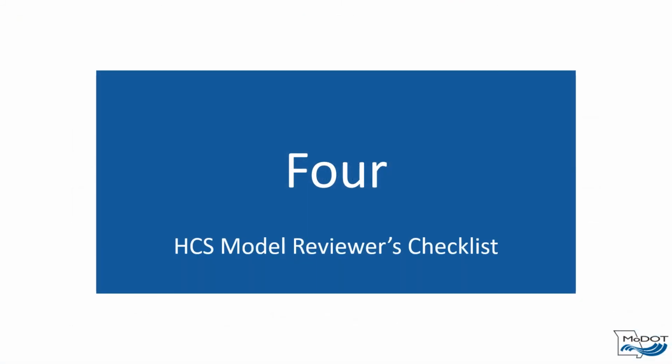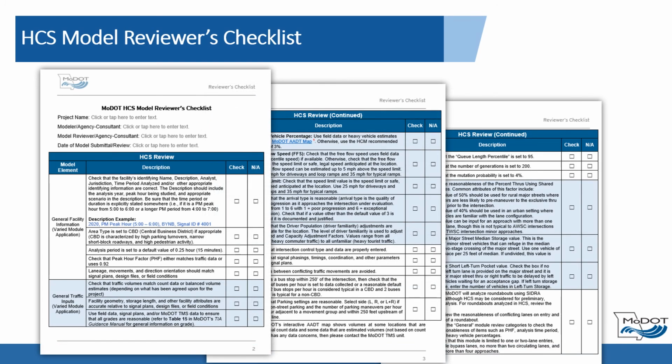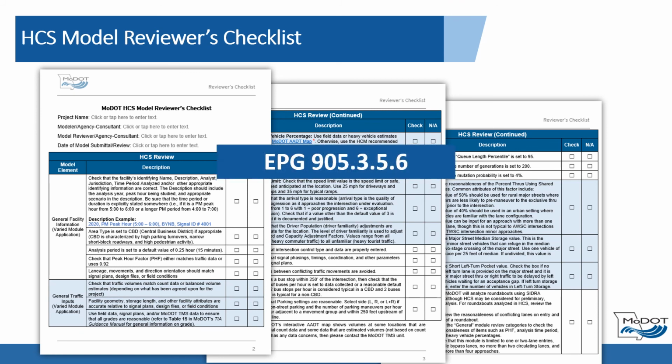The last step in the HCS process is reviewing the HCS checklist. Every HCS model submitted to MoDOT will be reviewed by a member of MoDOT staff using MoDOT's HCS Model Reviewers Checklist. To encourage agencies and consultants to review their work prior to submitting, this checklist has been made publicly available in EPG 905.3.5.6.